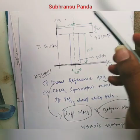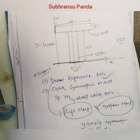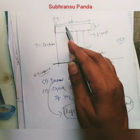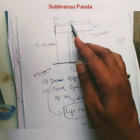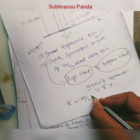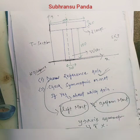We just go to the figure. The length of the flange part is 100 units. We can take the largest length from the reference axis. Where is the largest length? Because there are two sections. The T section has a flange and a web. So what will be the largest length? This is the largest length, 100, the largest distance in the x-axis. So the x bar will be 100 divided by 2, which equals 50. Manually we can also calculate, but to simplify, the question is given like this. So if the section is symmetric, we don't have to calculate according to the symmetricity.